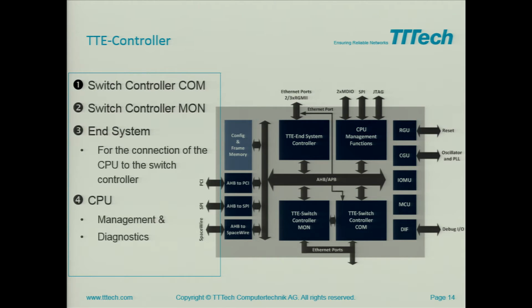The switch here, which I have not put on an additional slide, has 6 gigabit ports plus 19 100 megabit ports. So the switch engine here is capable of 16 gigabit ports throughput, and if the whole design is running on the chip, it consumes 1.5 watts running at 16 gigabit full data speed.